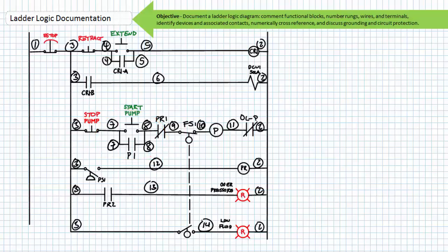All in all, it looks like we top out at wire number 14 for this particular ladder logic diagram. Note this is 14 wire numbers, not 14 wires. As I previously stated, wire numbering is better thought of as node numbering. A lot of wires lead from node 2 and 3. However, they're all connected to the same place.